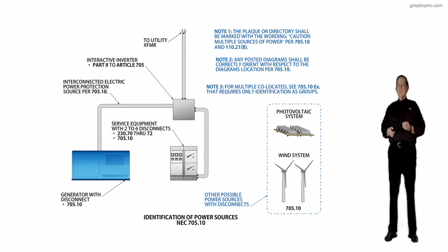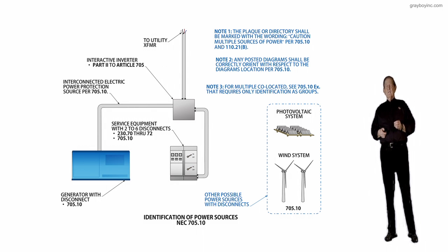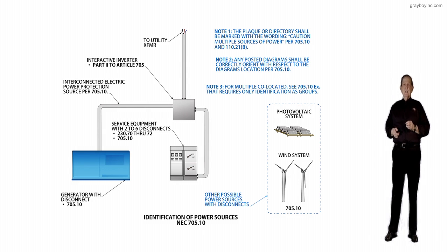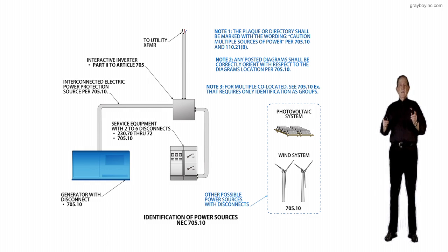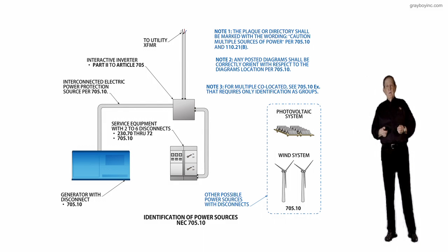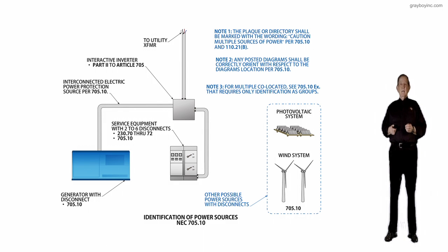I believe that's the right section, 230.71(B), and you look at item 3. My memory serves me correct on that section. But you're referencing 230.70, 230.71, and 230.72 when you deal with the service disconnecting means.